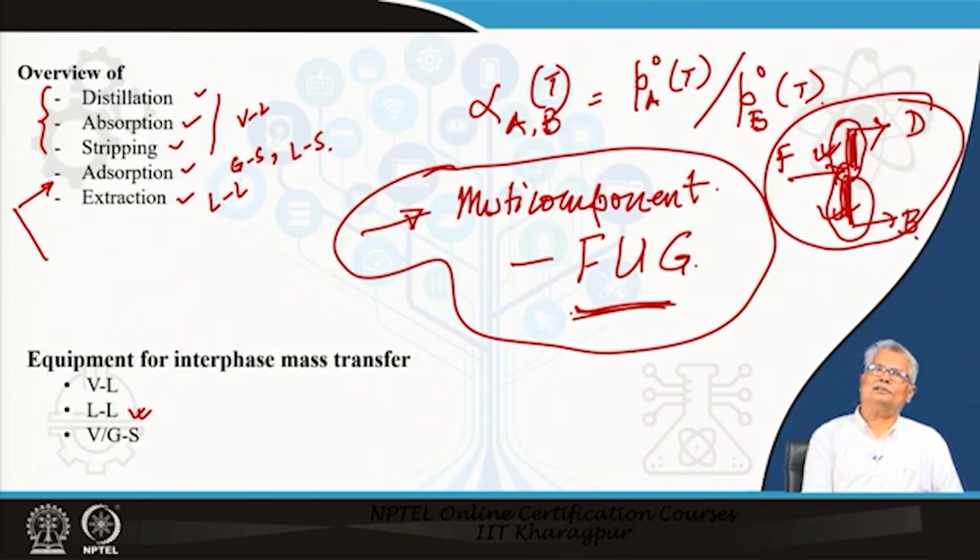So, that is the process of adsorption. Similarly, you can also remove some coloring material which may be present in a liquid stream, for example, in an effluent water, and get it adsorbed by passing it through a bed of activated charcoal or activated carbon.